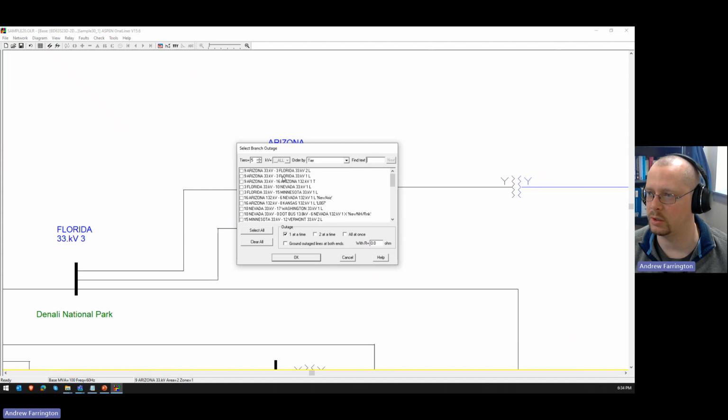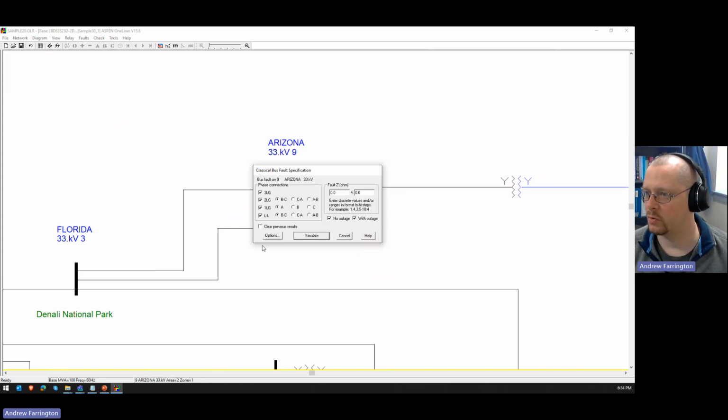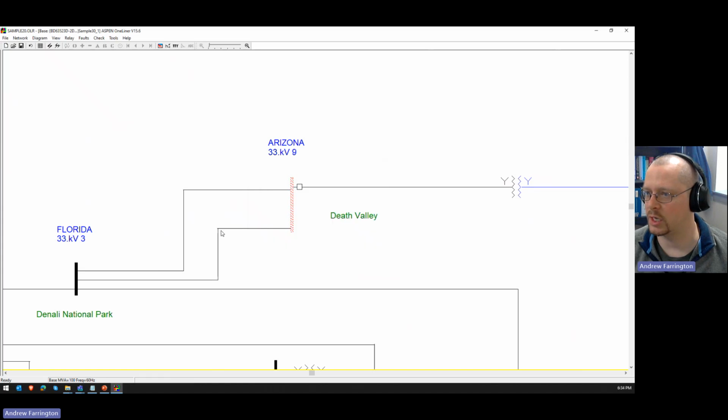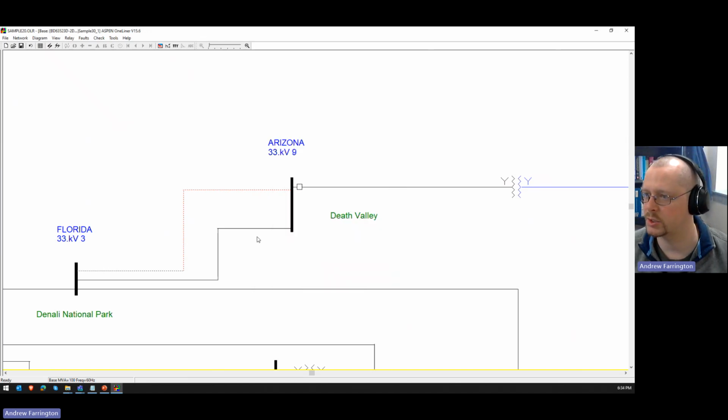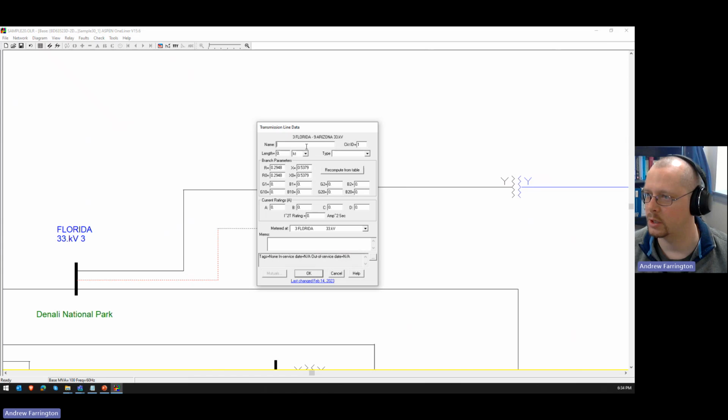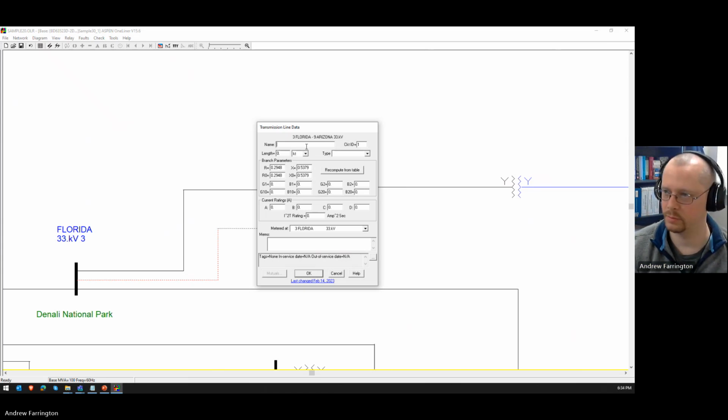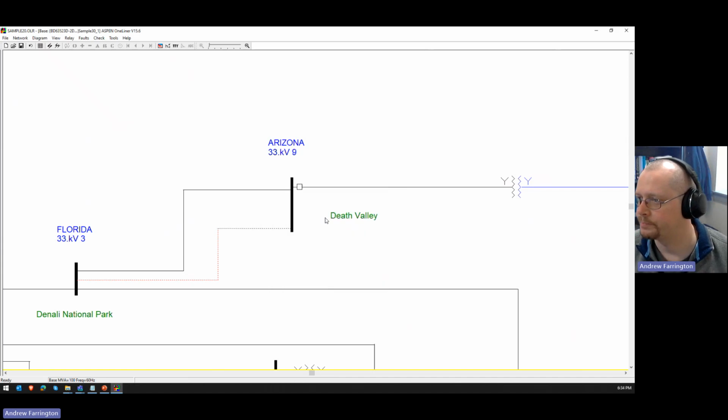That's so that the lines or the elements always have a unique name so that Aspen One-Liner knows what you're trying to do. But how would you know which line is which? The reason you couldn't really tell without going and clicking on it is because these lines aren't named. But if you do have a name for the line, let's say we call this one test and this one test 2, sure.